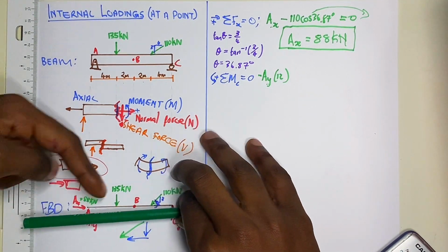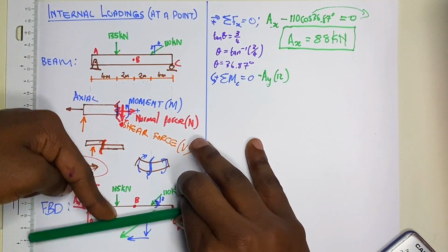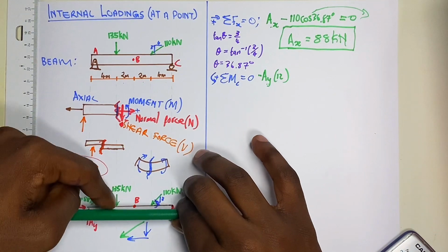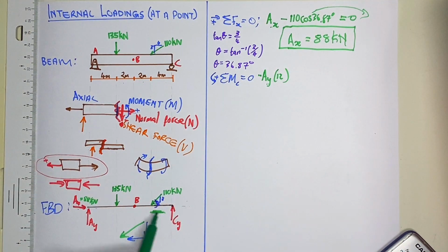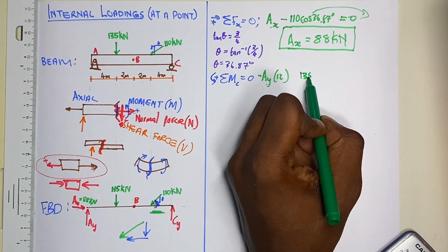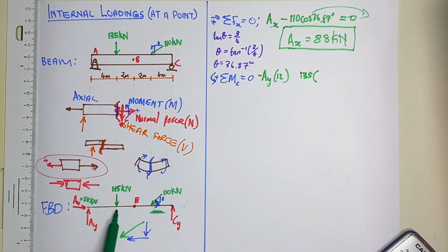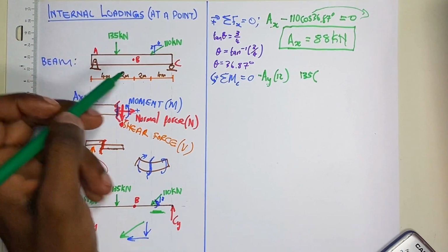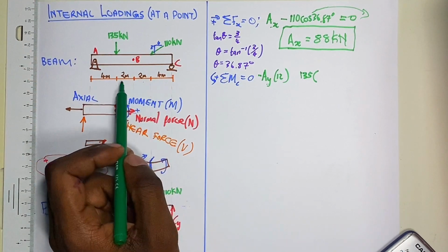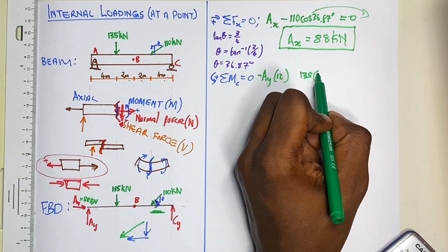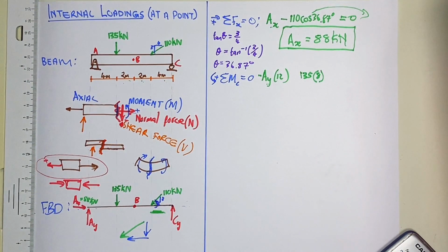About C, this force is causing a rotation or a bending moment about C. So I will write 135. How far is it acting from C? Remember, we must take the magnitude multiplied by the distance from which it is acting. So we have 4, 6, 8. So it is acting 8 meters away.